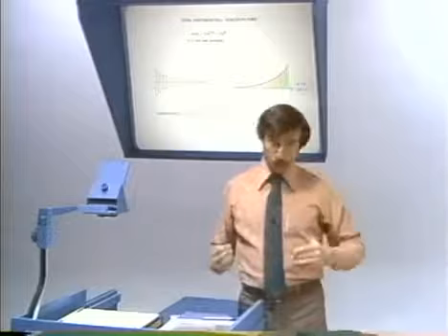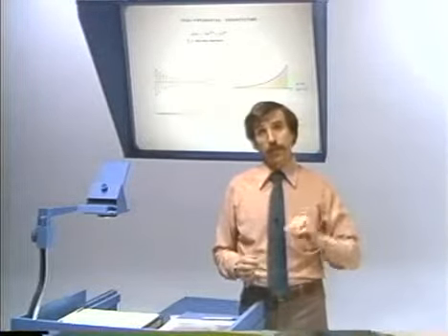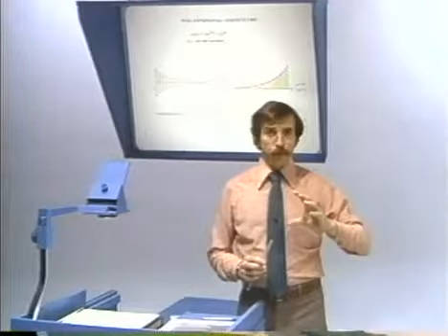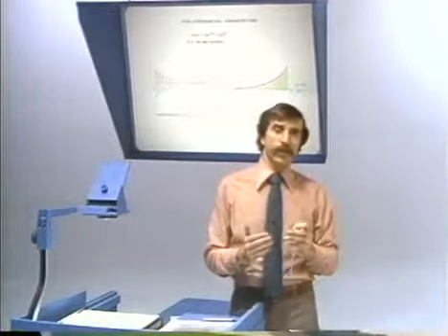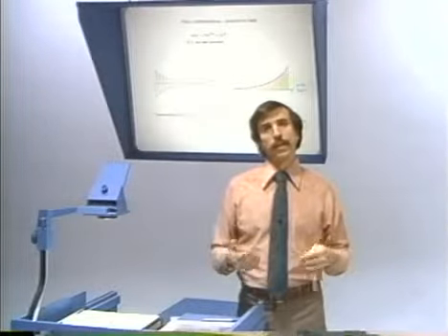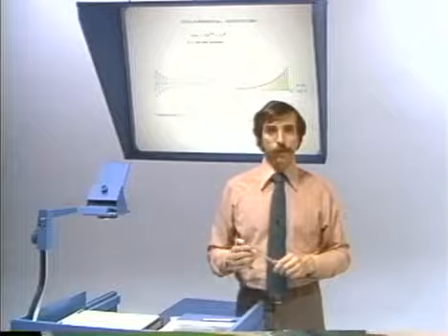Something to think about is what happens if alpha is negative, which is, of course, a very important and useful class of real discrete time exponentials also. Well, it turns out that with alpha negative, if you try to express it as c e to the beta n, then in fact beta comes out to be an imaginary number.